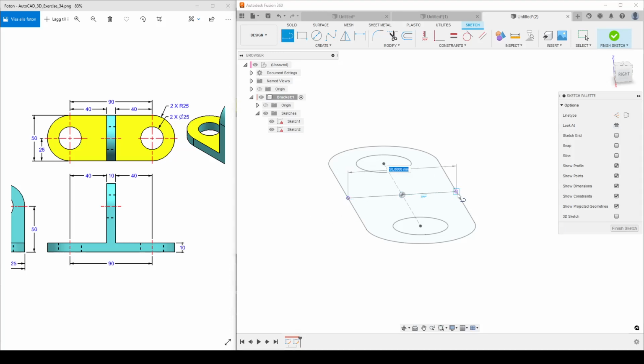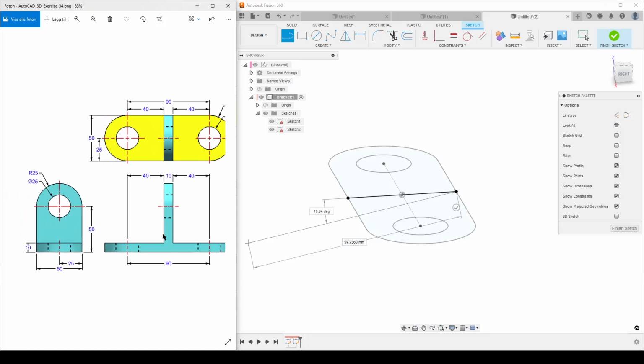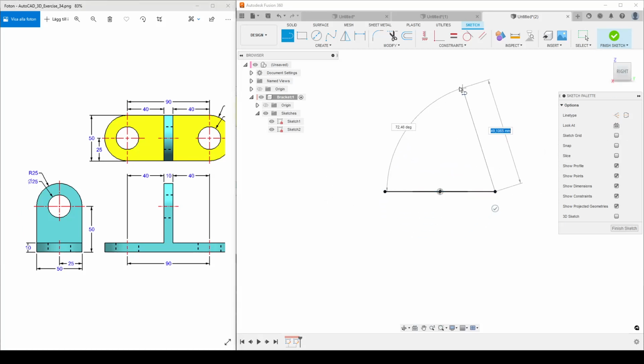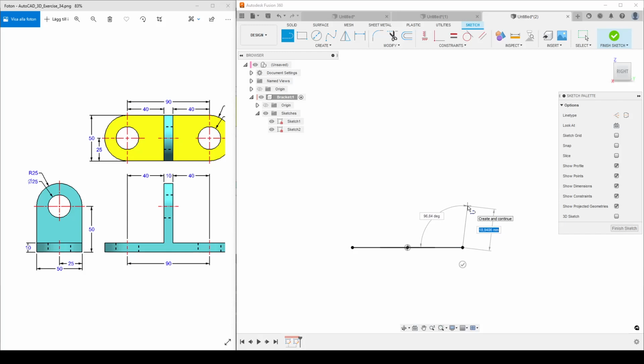By doing this, I don't need to add the 50 millimeter dimension. Let's move this over a bit. It's 50 millimeters here, so I don't need to do that. So let's look at, look straight at things. It makes things a bit easier. Let's use Fusion slightly, helping us add our constraints. You can see if I move here, I get the little square corner showing I have 90 degrees or perpendicular.